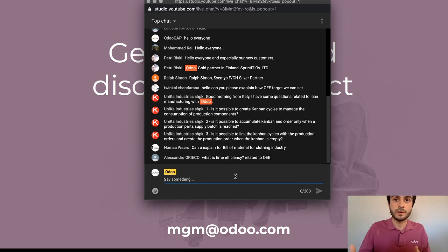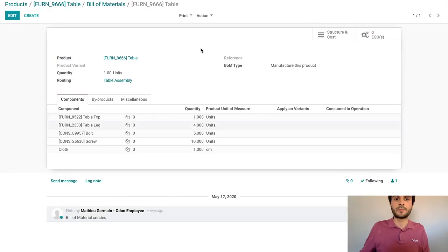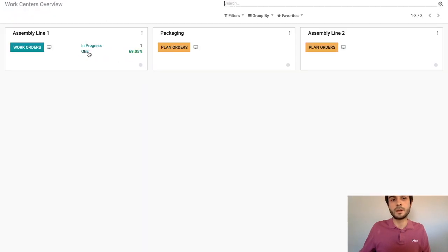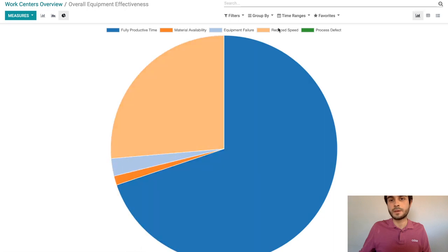And if you go above it, well, the OEE will register that extra time as reduced speed, as we call it, and then it will indicate here in the OEE that for the reduced speed, which is this part over here, about 25% of the manufacturing orders apparently are operating on reduced speed. It means that you are simply taking more time than what was expected in the beginning.